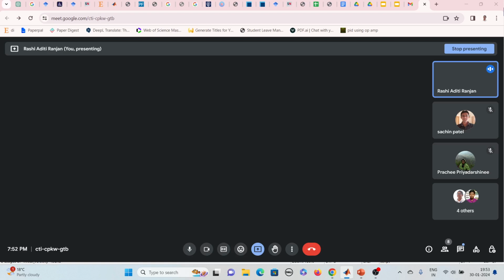Okay. Then I have defined options. This you can ignore as of now. We'll just keep it like this. This ODE set and relative tolerance and absolute tolerance, I'll take up in the further classes. This is not required as of now for simple equations. Okay. Then I have defined t comma z. There are two things that I'm getting after integration. One is t and another one is z. Z is our variable, which includes the velocity and displacement both.